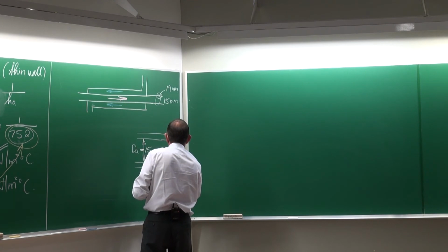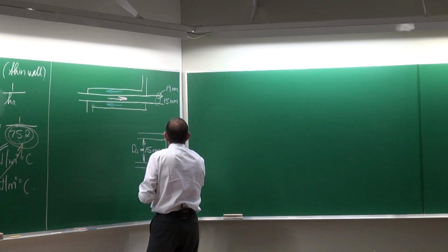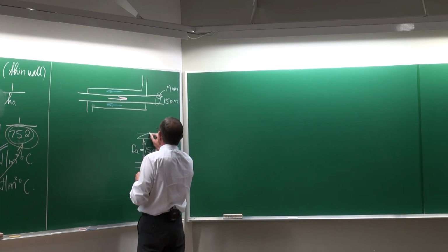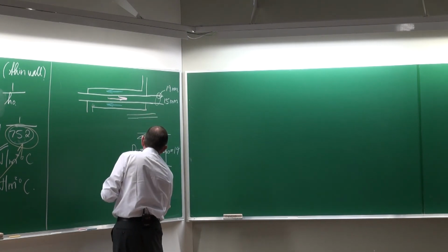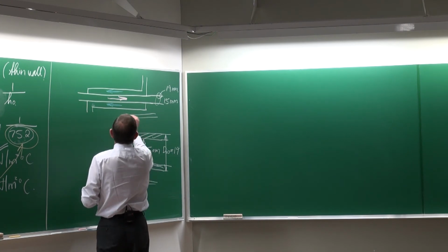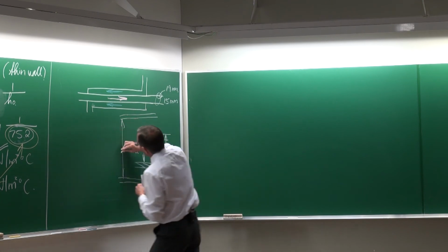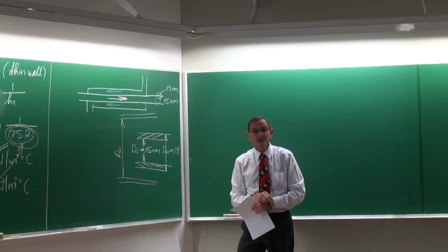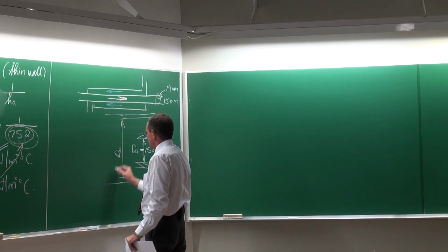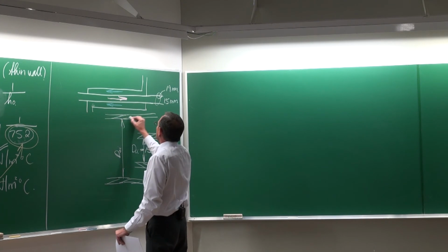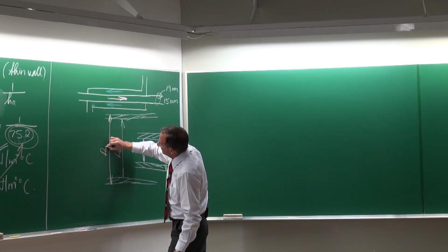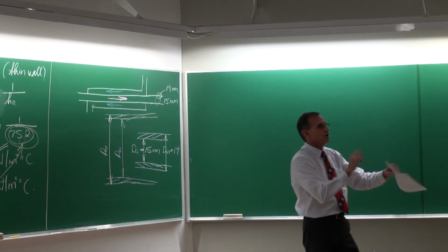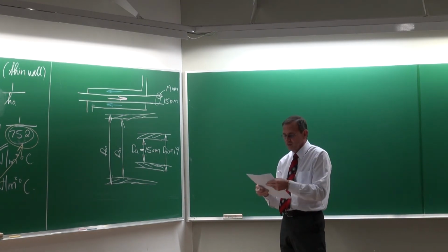And then that diameter, again of the inside tube, but on the outside, is equal to 19 millimeters. So there's the tube wall like that. While if this is now the annulus, we would typically indicate that diameter as the outside diameter of the inside, and from there to there, the outside, the outer tube, the outer diameter on the outside of it. So there you see the different types of notations that can be used.